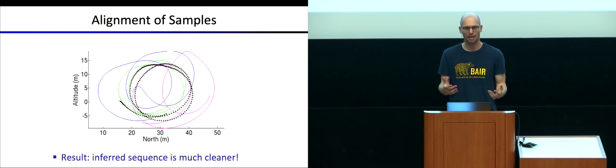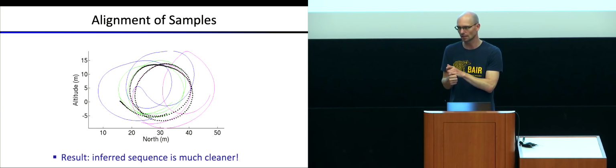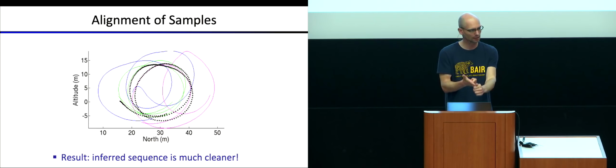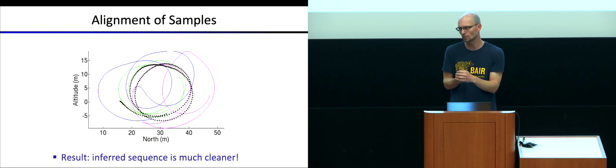Okay, so now we're set. We have collected data to learn a dynamics model for the helicopter. We have collected data to learn the target trajectory. We can now penalize: our reward would penalize for deviating from the target. And then we can run reinforcement learning in simulation, let's say, in this learned simulator to find a good controller and run it on the real helicopter.